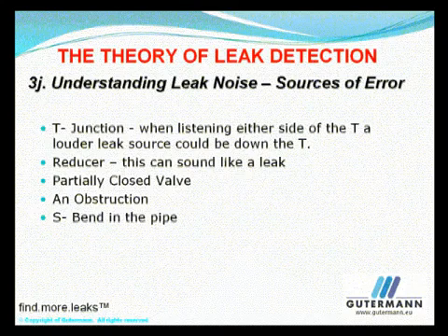Reducers, partially closed valves, obstructions in pipes, and S-bends often sound like a leak, so it helps to know the system you're working on to avoid these mistakes.